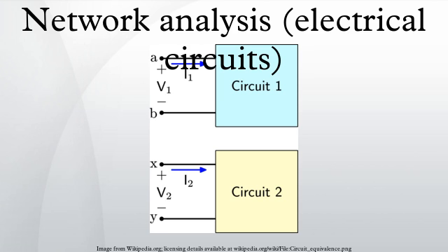Graphical method of DC analysis. In a great many circuit designs, the DC bias is fed to a nonlinear component via a resistor. Since resistors are linear components, it is particularly easy to determine the quiescent operating point of the nonlinear device from a graph of its transfer function. The method is as follows. From linear network analysis, the output transfer function is calculated for the network of resistors and the generator driving them. This will be a straight line and can readily be superimposed on the transfer function plot of the nonlinear device. The point where the lines cross is the quiescent operating point.